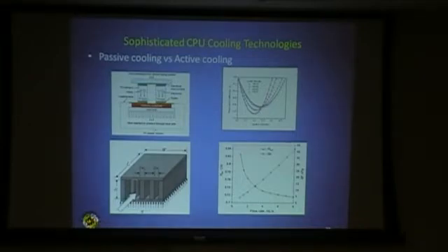You can place these very close to those thermal hotspots, and this current basically forces you to expend some energy for providing cooling. So that's another dimension of optimization that you can focus on. Another interesting device that these guys are focusing on is called microchannels, where you fabricate these channels in high density at the back of the chip, and you can flow some chilled coolant through it.